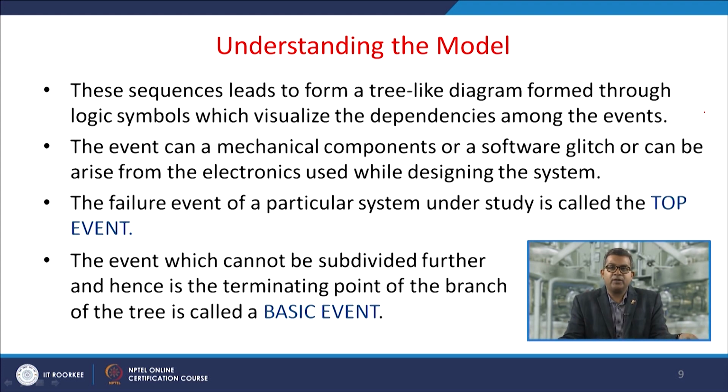dependencies among the events. Now the event can be, you can say, a mechanical component or a software glitch, or can arise from the electronics used while designing the system. So the failure event of any particular system under study is called the top event. Now the event which cannot be subdivided further into different branches or subsystems, and hence is the terminating group of the branch of the tree, is called the basic event.